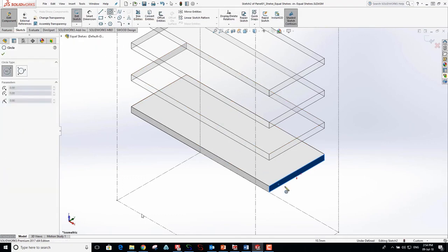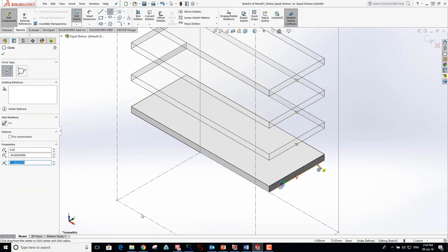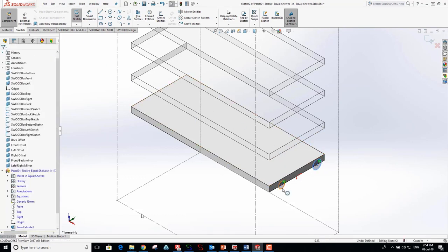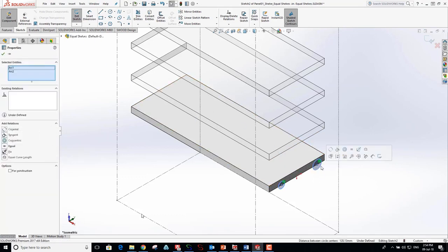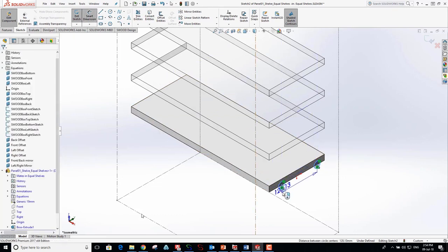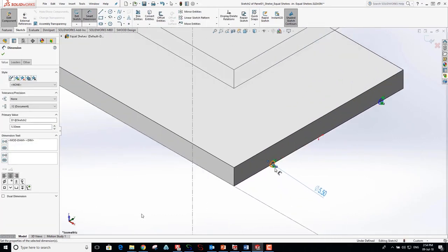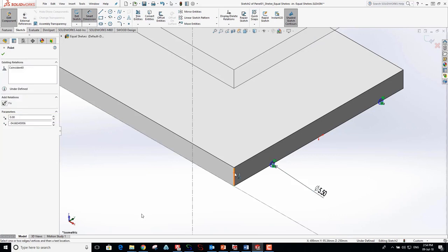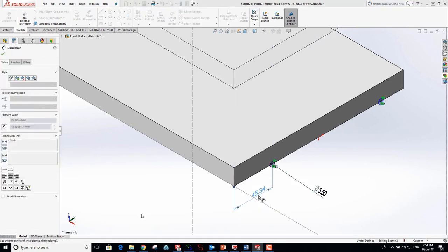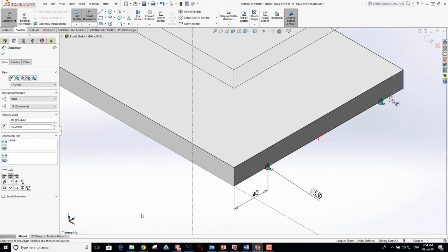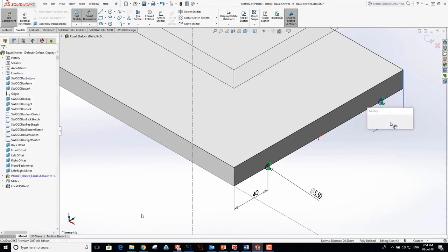So we're first of all working with some top-down assembly modeling techniques whereby we're editing the panels inside the SOLIDWORKS environment. And what we're doing here to start with is just creating ourselves a sketch on the side of the panel, ready to create those cut extrudes that are going to be needed to locate the shelf studs inside of the shelves. So we just used a couple of sketch relationships there, particularly the equal sized one to control the diameter of the circles, and finally putting in some dimensions to control its location.